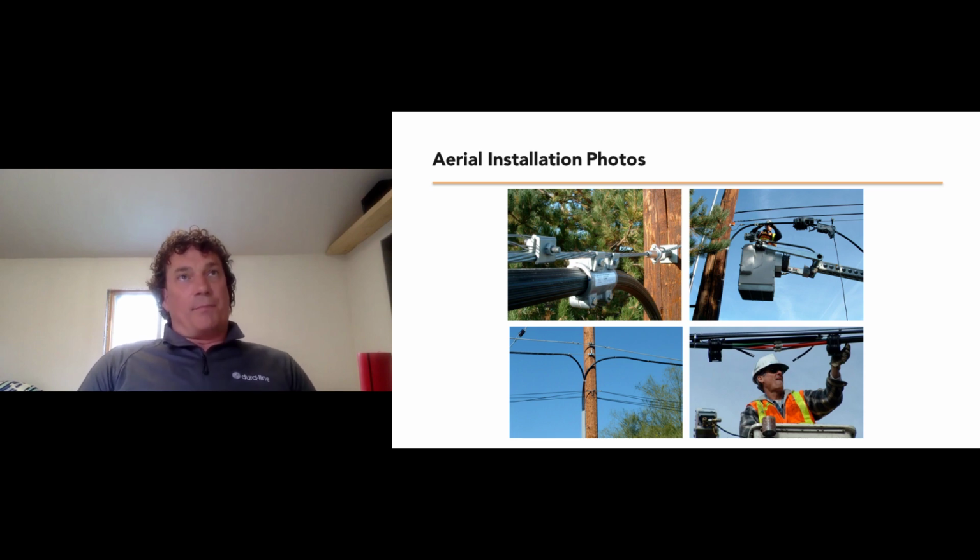Yes, there's a bunch of different reinstatement materials, and great question. Some work well in certain environments and others work well in other environments. Some of the problems that we have in Canada with microtrenching and that reinstatement material is frost cycles. We get those freeze-thaw cycles over and over again throughout the month, and the freeze-thaw cycles can heave and move that product underground. So it's very important to have those reinstatement grouts work for the environment that you're in.